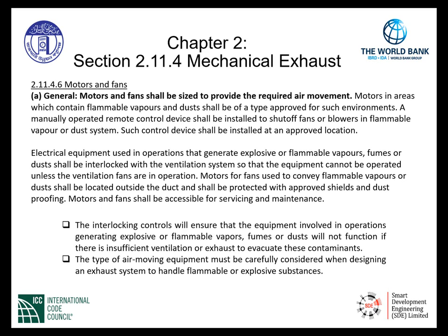The controls must be interlocked to prohibit the operations of the equipment that generate these contaminants. The type of air-moving equipment must be carefully considered when designing an exhaust system to handle the flammable or explosive substances as well.